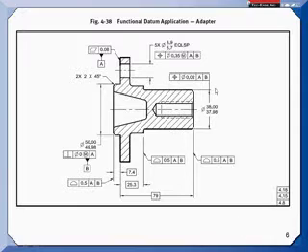As I look at the drawing here for this adapter, they've made this face primary, takes away the 3 degrees of freedom. They made the pilot diameter secondary, but they didn't make these interfacing mating features datum features. They just toleranced them. Okay, we're locating this shoulder with profile, and we're locating this diameter with a position tolerance. So they're toleranced back to A and B, but they didn't make them datum features. And that's why I was showing them in blue in the assembly.